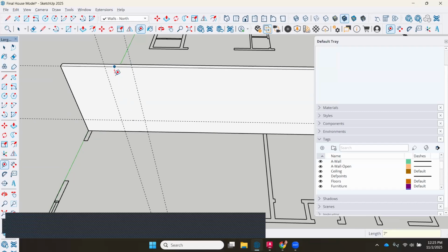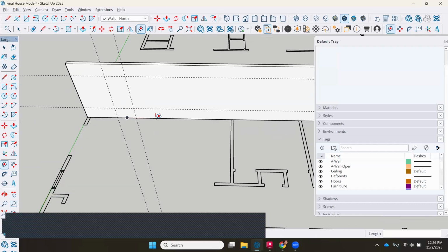Then you've got to have at least a foot of header up above it, so there's enough wood encasing the window so your wall is stable. You can write 1 foot or 2 feet, whatever you think, but you're going to keep this. So that's 8 feet. The other thing to pay attention to is your doors are at 7 feet. Depending on how you're designing your house, if you want all your windows to line up with your door openings, then your window is only going to be 7 feet tall. I'll use that as a reference now.